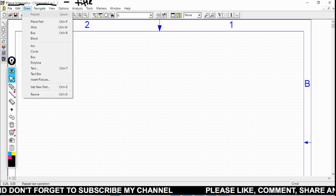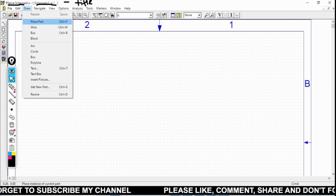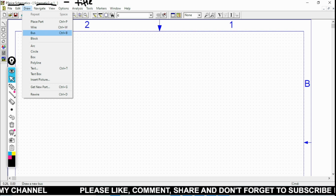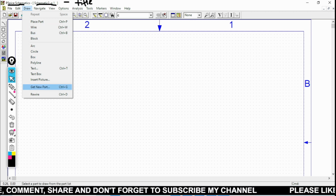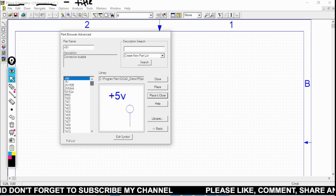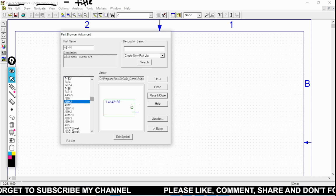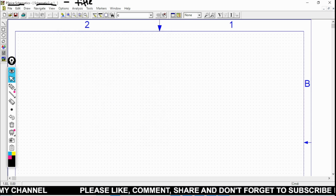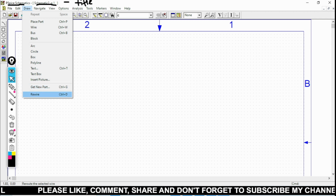Then in draw, we need the part called place part, where we are going to use the shortcut Control P. For wire, we are going to use the shortcut Control W, and for bus, we are going to use the shortcut Control B. So this is from the draw menu. Here is the next important thing, that is get new part, Control G, where we can take the new component of electronics from that get new part. We can close it here. So this is the Control G get new part. And rewire, if you have to make the connection again, we can use the Control D shortcut to rewire the connection.